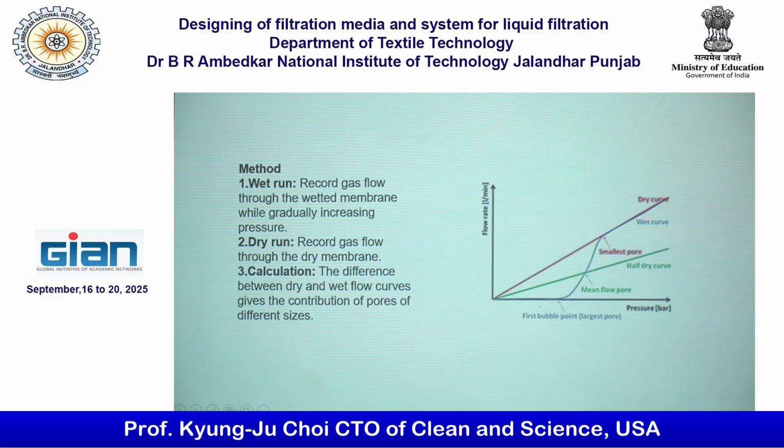You do the wet run. Wet run is this one. It starts once you pressurize a little bit, then you can see the first bubble comes out. That's the largest pore. That's right here, a starting point.